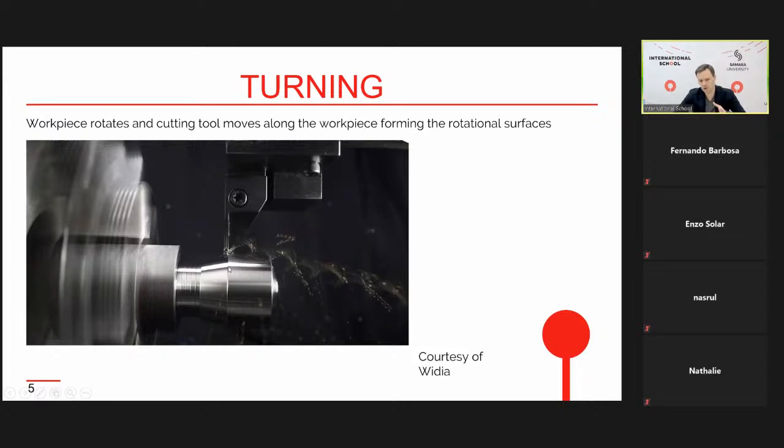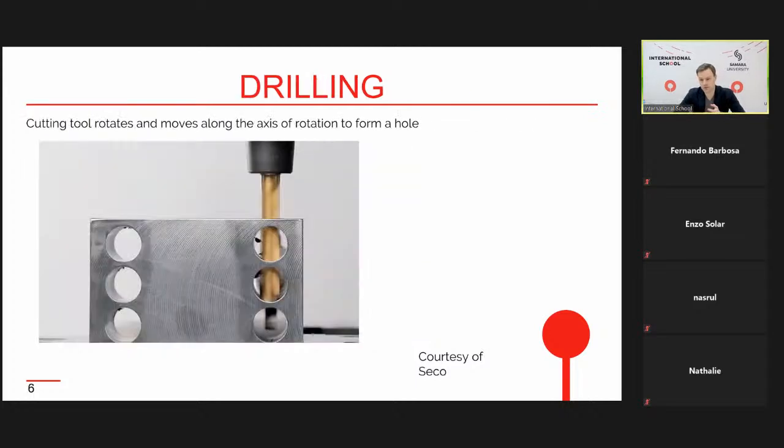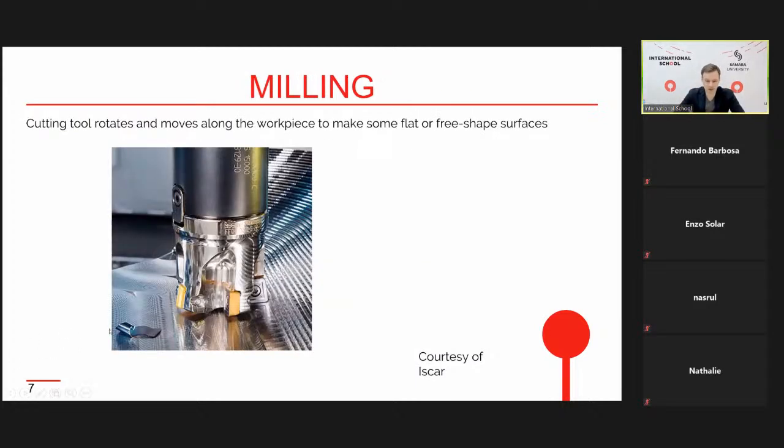This surface can be used in some assembly of parts. So it's a good surface, let's say. But this surface is poor or bad. Why? This is a rough process. When we cut some materials, we usually divide the process of cutting into some steps. The first step is a rough step, when we remove a thicker layer of material, but after the machining we have some rough surface.